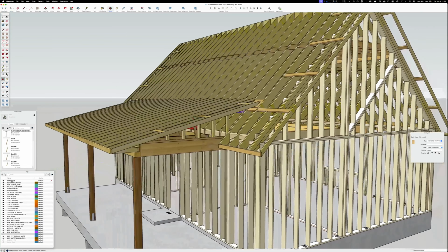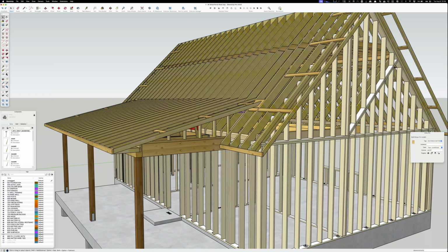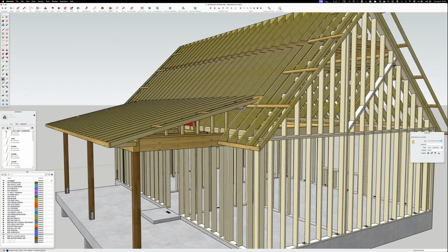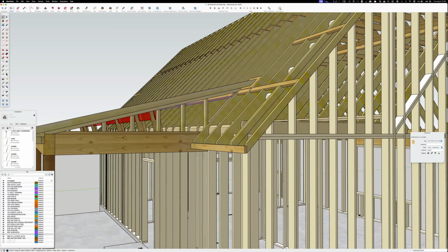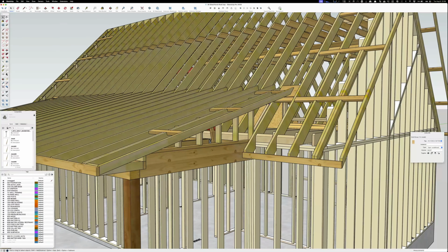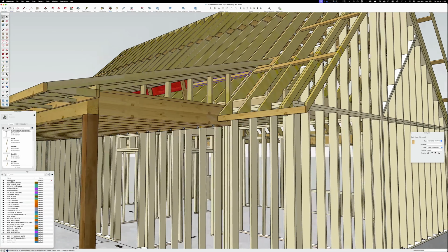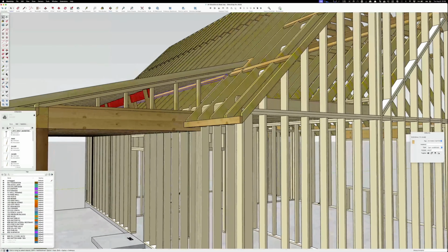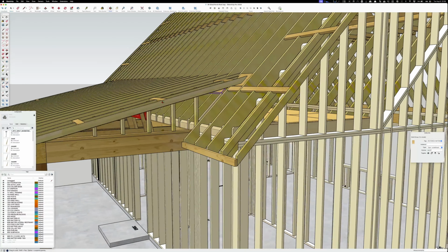And now one person can set all these rafters, because all you got to do is have them leaned up, either lean them all up in the corner or lean them along the back, pull them up, run them up here, lay them on this 2x4 so they'll be at the right elevation, and then shoot them in as you go, and then come around the inside and line the tops up with the popped line you made, and it should be right on top of that 2x4. And then shoot them in.